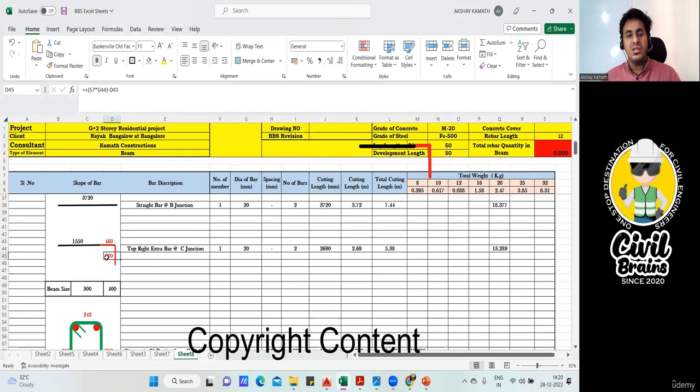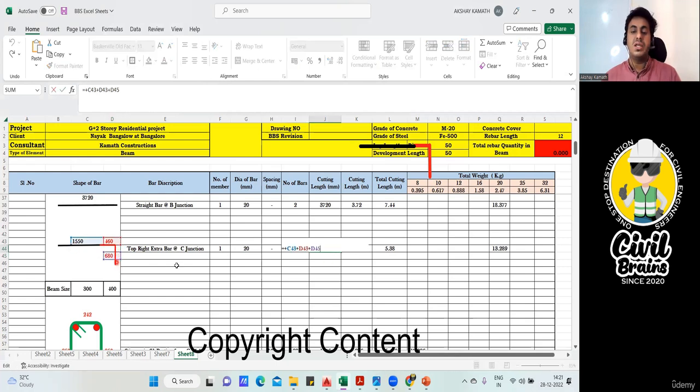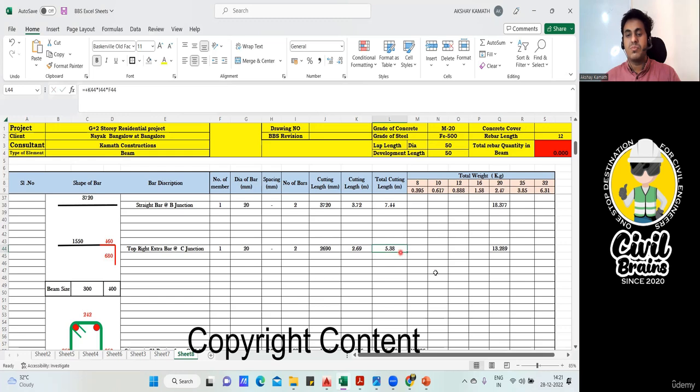And how is it 680? 680 is 57 into the diameter of the bar, minus 460, which will give me this particular depth. Got it? So my total cutting length will be 1550 plus 460 plus 680, which gives me 2690. The cutting length will be 2690 divided by 1000, which gives 2.69. So this is the cutting length of one bar. To find the total cutting length, 2.69 multiplied by number of bars into number of members gives me the total cutting length, which is 5.38.